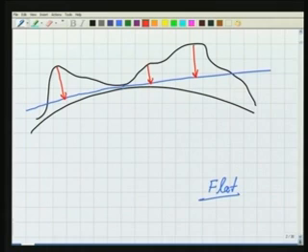Okay. So what we are doing is the same thing as the example I had shown here. This is also part of the earth, but I considered here this floor, and the floor is flat. When I projected my points onto the ground, I didn't consider the curvature of the earth, rather I simply measured the distance between the points in a horizontal plane, because I know for a small area it doesn't matter.